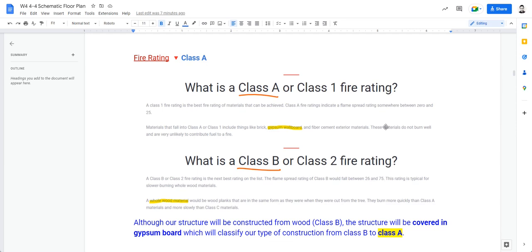But if you cover that wood with chipboard, then you actually provide a barrier because they don't really burn. The paper will burn. Gypsum has paper, and the paper will burn, but because of the material inside, it will not burn immediately. It would burn eventually, but there's some rating now. So Class A would be rated in terms of fire spread or fire penetration.